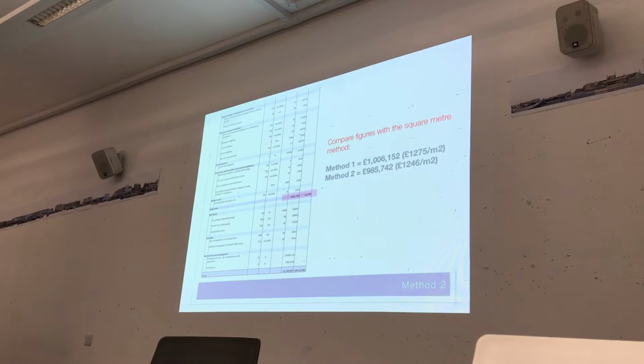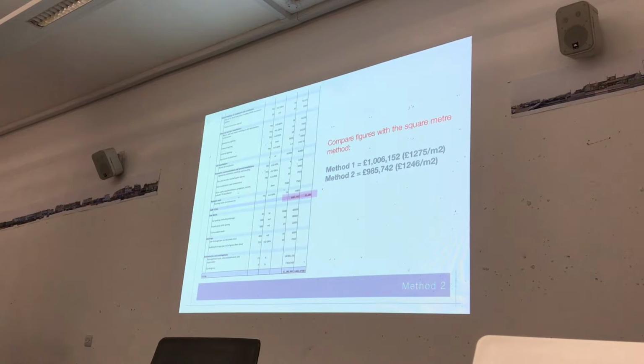At the back of the Spons book, I can't find the page, but I'll open it up in a minute. There's a whole load of different elements. If you're using a cost model, there are going to be things in there that aren't the same as your building. So you're going to have to find within Spons something that is more like what your design dictates in terms of its finishes. If you're looking for external cladding that's not what I've got in that cost model, then you need to find something that's like that and then put the rate in.